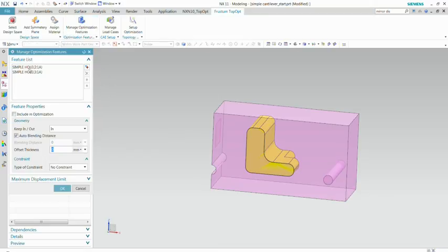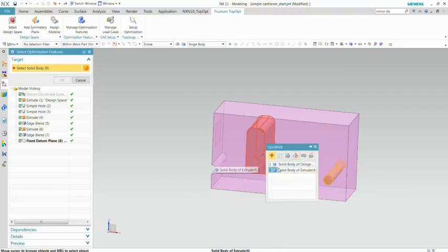Further on, we're going to say that around that central hole that you see highlighted over there on the left, we want at least 1 millimeter of material. For example, that we want a full zone for an axis. And at that location the part is also fixed, so the part cannot move around that hole. We're also going to define an offset around the right hand hole.